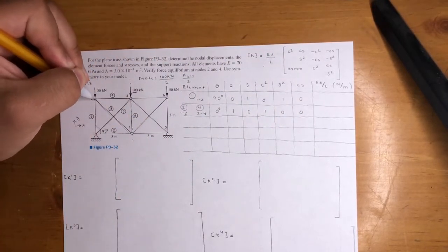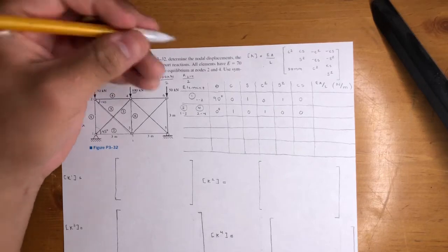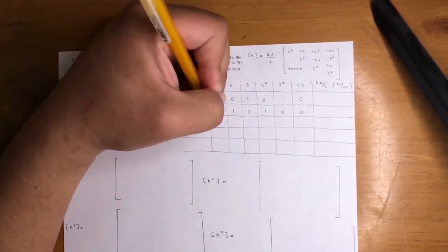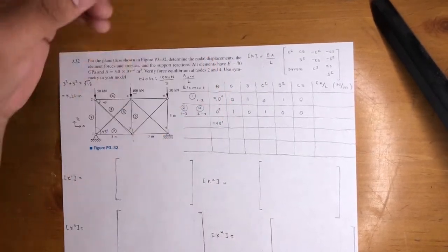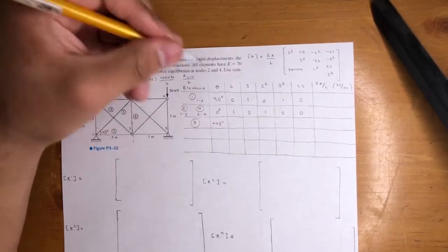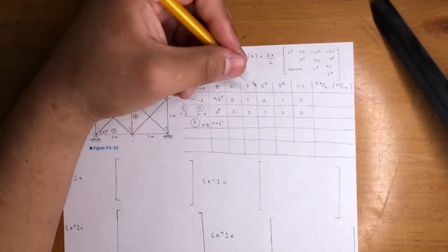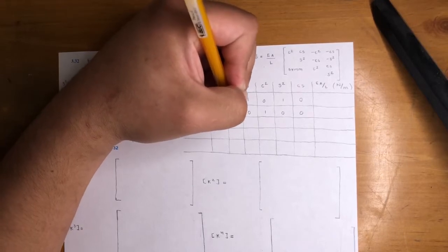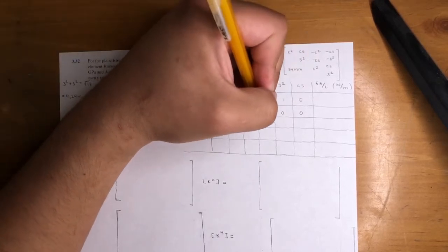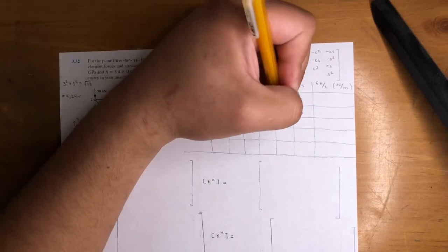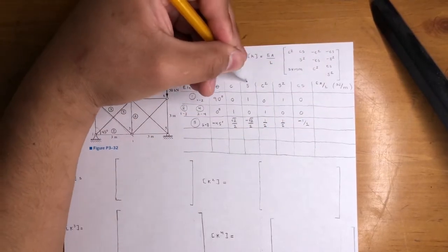Element 3 now, we're going from 2 to 3. That angle from the positive x-axis is negative 45. Or just 45 degrees, whatever. No, I mean, in this case, it has to be negative 45. But on the diagram, I didn't really have to draw a negative. That's just 45 degrees. That's for element 3. That goes from, again, 2 to 3. So we're going to make that little note, 2 to 3. And take the cosine and sine. We will get radical 2 over 2, negative radical 2 over 2. What else? We'll get half when we square cosine. We'll get half when we square sine. And we will get negative 1/2 when you multiply cosine times sine.